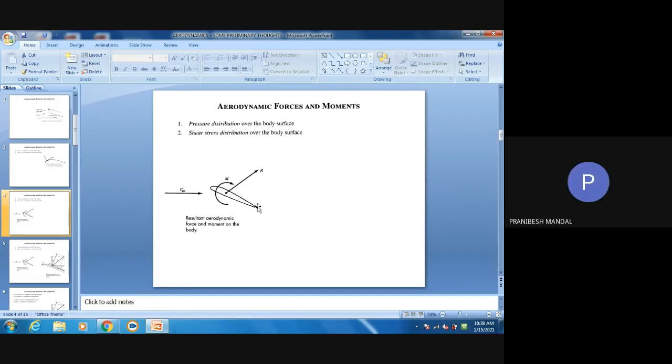Here I have shown you the general configuration of angle of attack, which is positive. If it is in a nose down position, the angle of attack is negative. Generally, it is nose up position. If it is in nose down position, then we have to consider the angle of attack to be negative. Actually, I have considered this nose up position to make you realize about the angle of attack. It doesn't necessarily always be nose up, obviously.